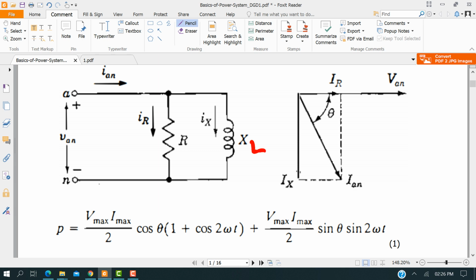So the total current is divided here, and where is the resistance? Earlier we said that there is no phase difference between voltage and current, so the phase difference theta is zero. Here we see that for a pure inductive circuit the current lags behind by 90 degrees. For a capacitive circuit, with a voltage and the current IC, it should be 90 degrees leading, but that holds only in a pure capacitive circuit. Okay, and the resultant graph would be here in the middle of them.